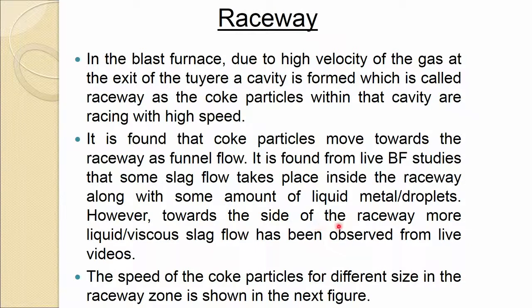However, towards the side of the raceway, more liquid viscous slag flow has been observed from live video. Of course, this was not there in the video due to some proprietary reasons, but the dissection of the blast furnace in the live video shows there is plenty of liquid flowing in between the two tuyeres or at the side of the raceway.